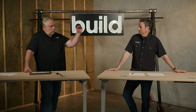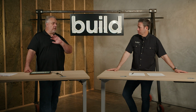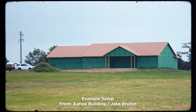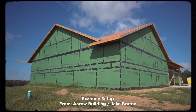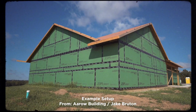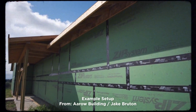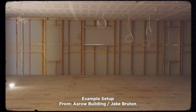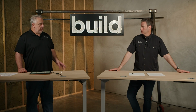And we put the drywall in on the second floor lid after we put the roof on, and it was a slab on grade house. So it was basically just a green box. And then we tested it. So concrete slab on grade, kind of like my tabletop, walls. And then the framed roof had the air barrier at the top with drywall. So we had our continuous air barrier, no punctures, no penetrations, no windows or doors, just the one door opening where we had the blower door test. And it performed amazingly well.